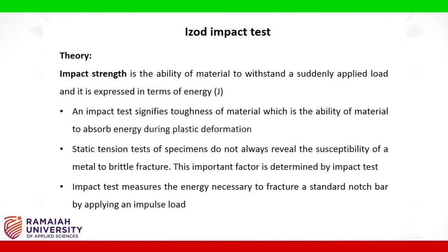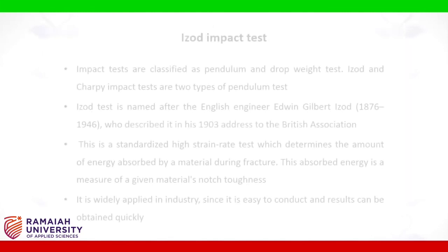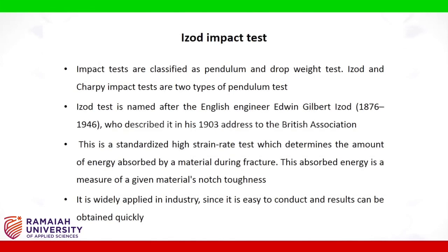Impact test measures the energy necessary to fracture a standard notch bar by applying an impulse load. Impact tests are classified as pendulum and drop weight test. Izod and Charpy impact tests are two types of pendulum tests.